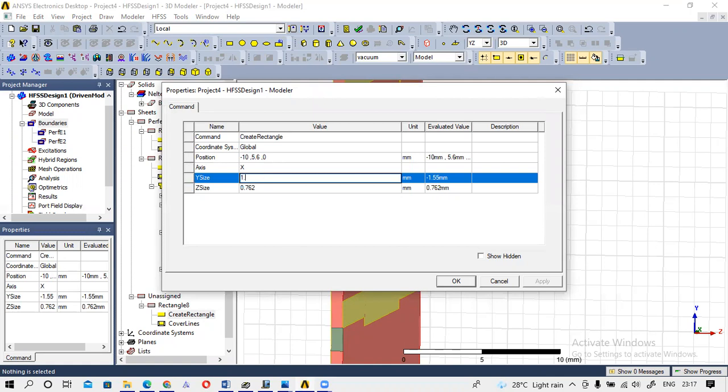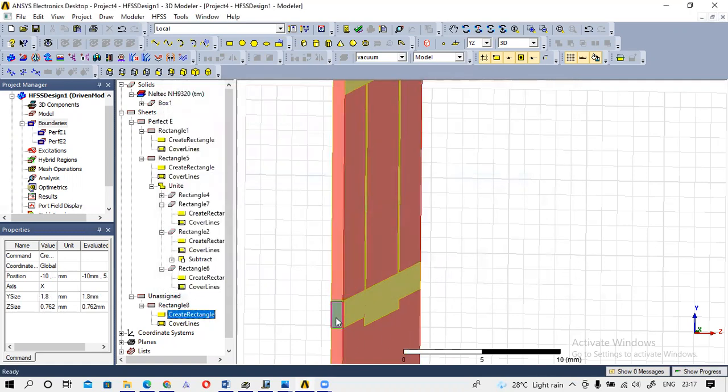So likewise, you have to think, and you have to fit that rectangle. Okay, that is very simple. You have to know the x, y, z coordinate. So you can see that now it is fitted, no? Fitted. And this is nicely fit with this area, and also this transmission line section and ground plane is also touched with this rectangle.